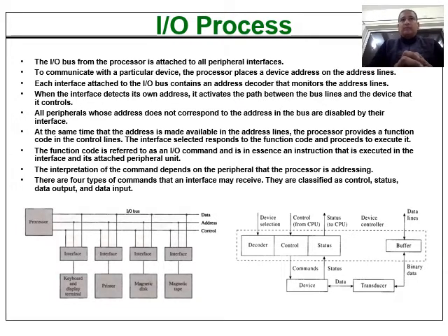When the interface detects that the address is for the device that it is controlling, it activates the device. Otherwise, it simply deactivates the device. So, depending on the address the CPU has put on the address lines, the device is either activated or deactivated, and that task is done by the decoder section.